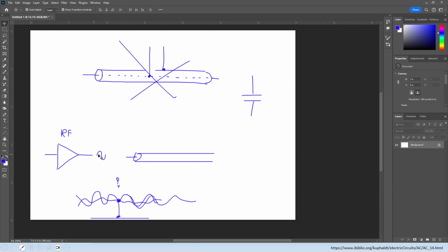All the power is going to smoothly be transferred from one thing to the other. And that's all the amplifier cares about. If the impedances are mismatched, then not all the power is going to get through. Some of it is going to bounce back, come back to the amplifier, heat that amplifier up, and so on. Usually it happens like that.